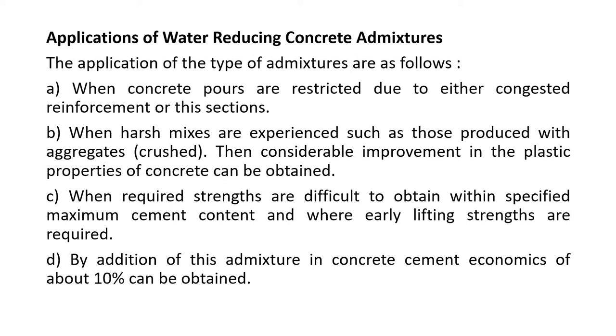It is also useful when required strengths are difficult to obtain within the specified maximum cement content, and where early lifting strengths are required. By addition of these admixtures in concrete, cement economies of about 10% can be obtained.